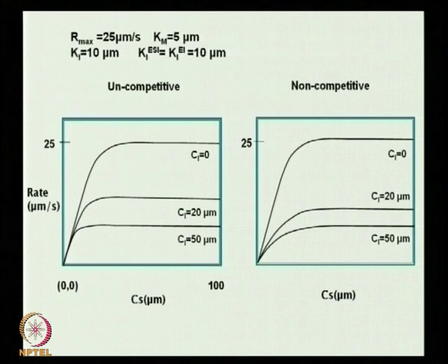So, as a result, say your flow rate is 1 liter per hour and you have a 10 liter reactor. Your residence time is 10 hours, right. Now, if you split it up into 4 different reactors, your residence time is 2.5 hours each, and your reactor volume is 2.5 liters each, okay.